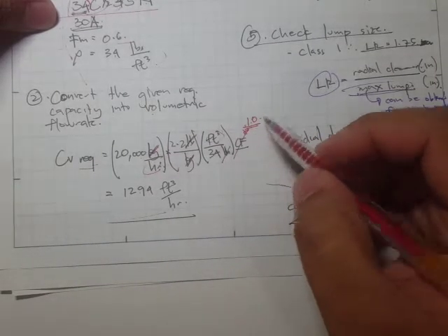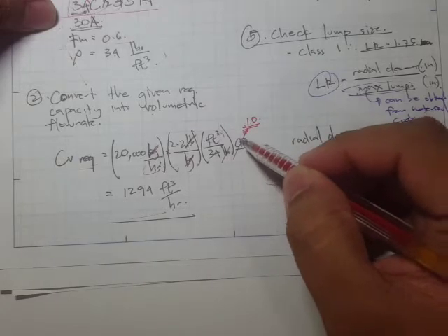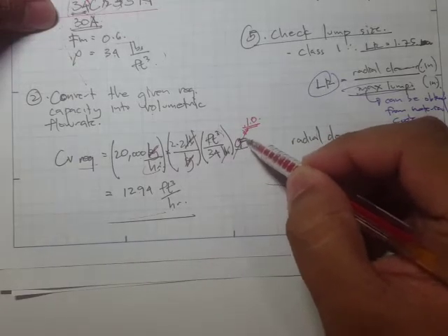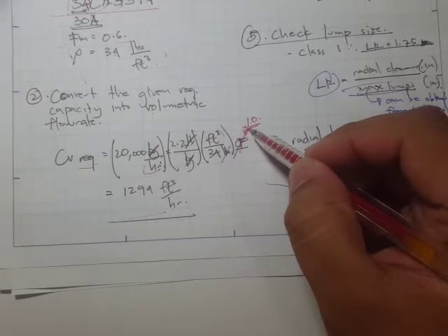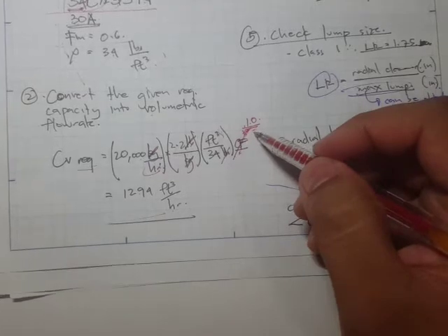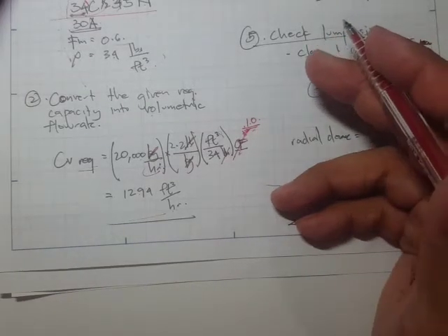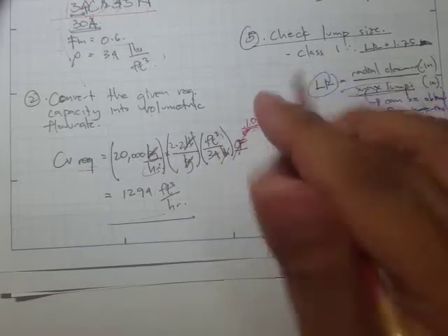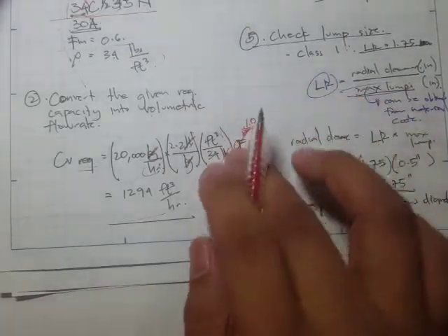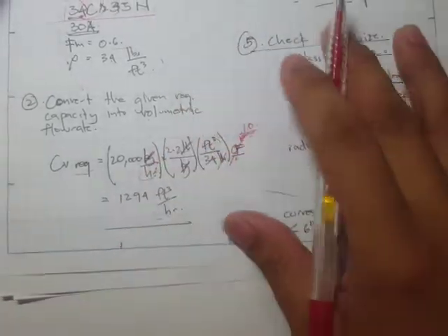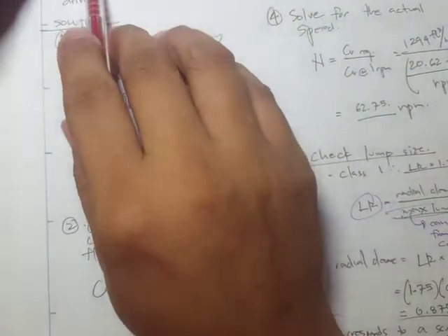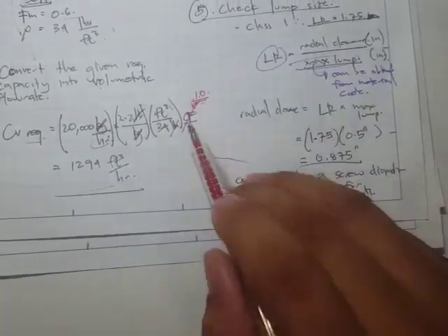Just a couple of notes here. In our lecture handouts, we have these capacity factors. This comes into play if you have other designs of flights, like for example, ribbon flights, cut and fold flights, and if you have also two-third pitch or short pitch. Actually, there are a lot of factors here that you are going to multiply. But for this specific problem, since we have a standard pitch and standard flight, that's just 1.0.